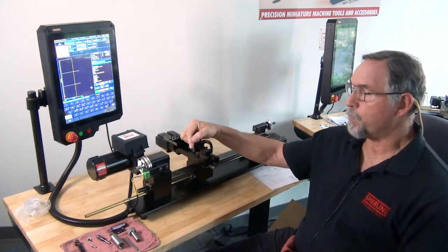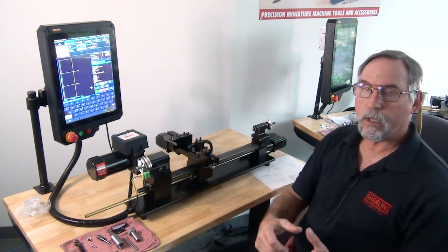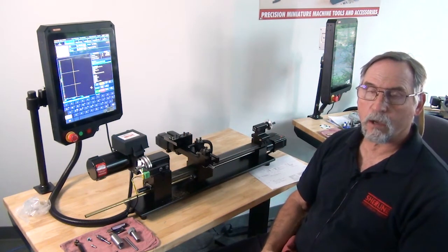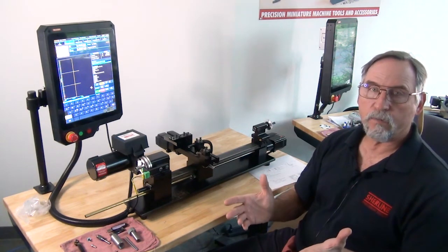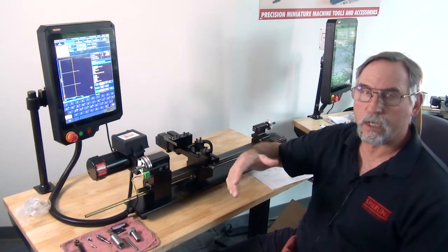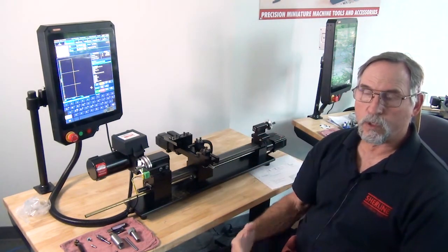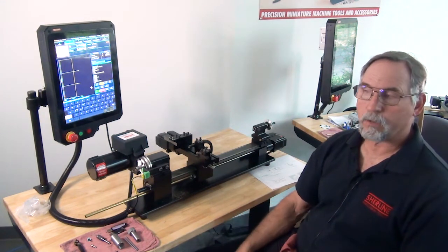Then it's going to go to 1 inch and feed out. At 1 inch, whatever maximum spindle speed you calculated with that formula, that value divided by 1 is going to be that value. So the RPMs that show on the screen should be exactly what you calculated using the SFM in that formula.